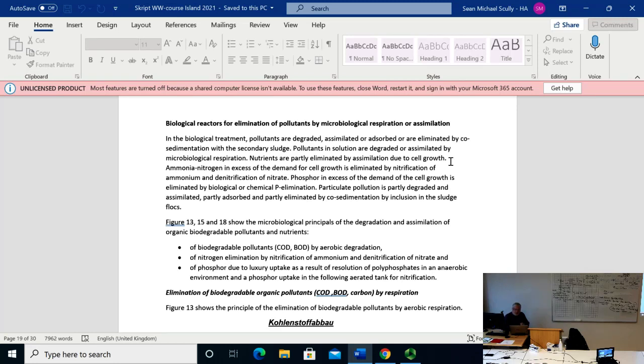Okay, in the case of phosphate, 80% are orthophosphates, which you find when you take the inflow and make a filtered sample. In the filtrate, you'll find 80%. So 20% is particulate, and from those 20%, again, 70% will be eliminated in the primary. It's from 20, 70%, 14% will be in the primary sludge, and 6% will be in the particulate phosphate that will go into the bioreactor.